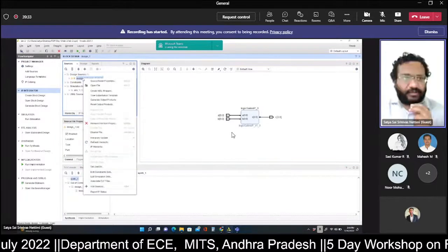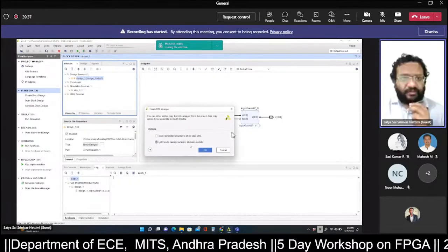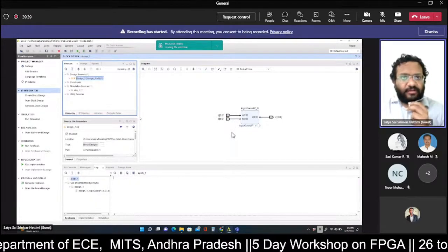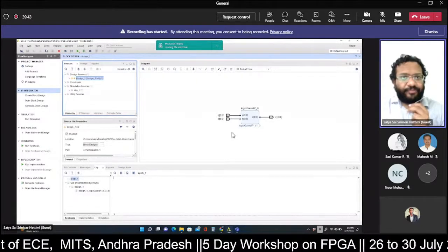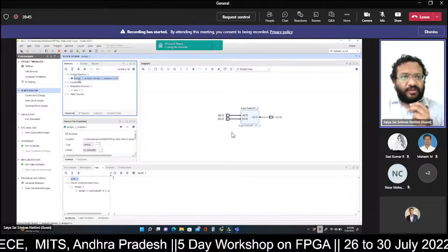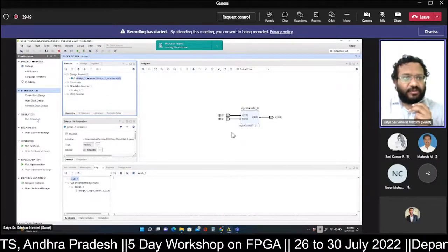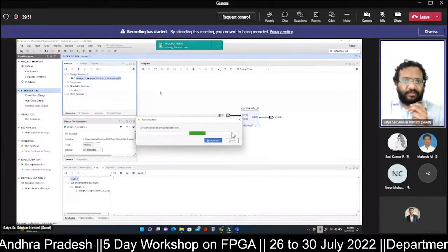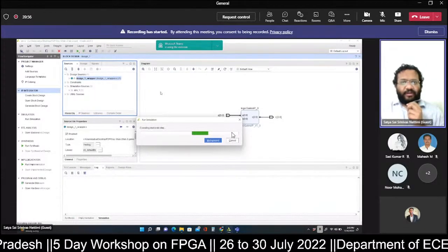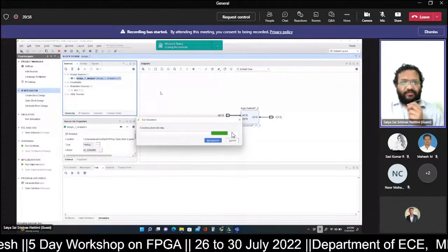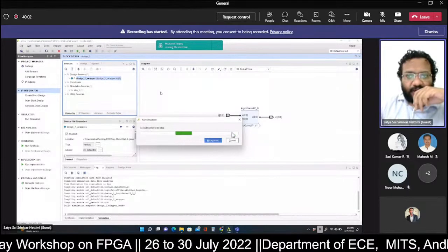Now select the design block design, right click on it, create HDL wrapper and click OK. Now the wrapper will be generated. For a quick verification, you can put it as top module and click on run behavioral simulation. Here I'm not writing any test bench. You can directly force the values since it is a simple XOR gate.